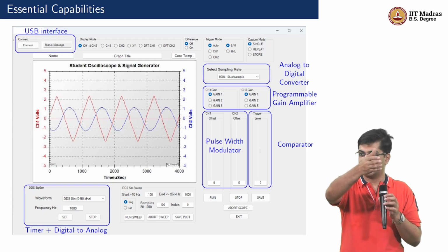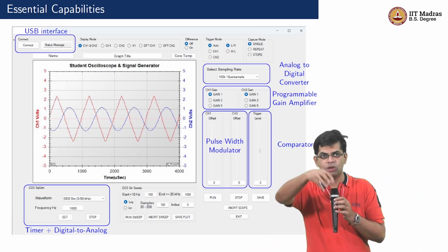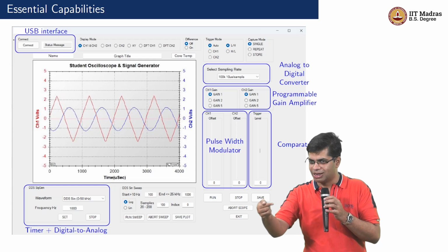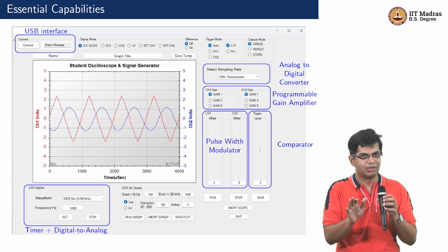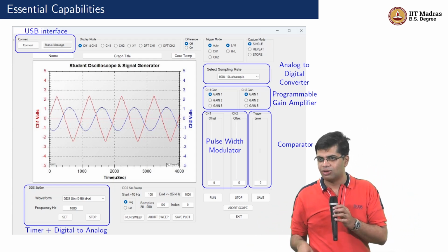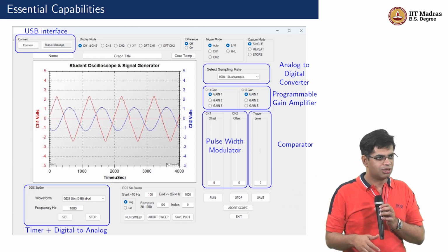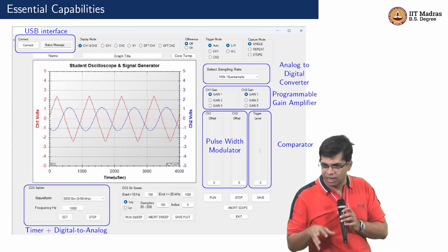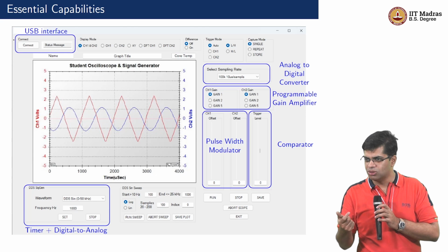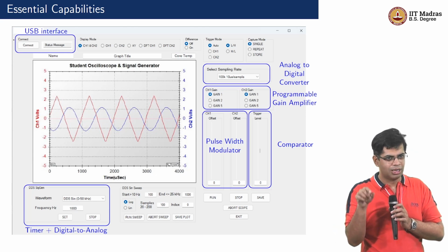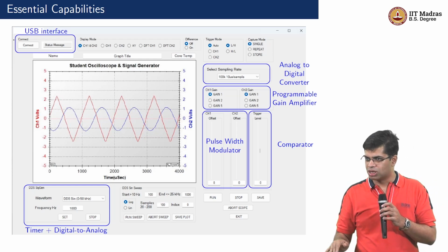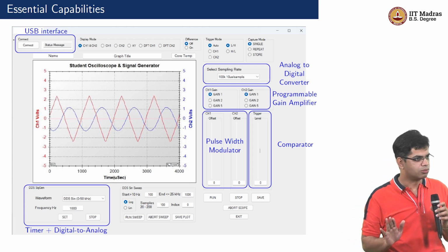You can buy a dedicated USB interface chip, or something like an interface board that you can then stick somewhere else. That's one option. Then for your ADC, you might have just an A to D converter chip that you then have to interface with some microcontroller. Or you would try and choose a microcontroller which is a system on chip, which gives you all of this functionality within the same chip. If you do that, your component count comes down, and it's also likely that your cost comes down.